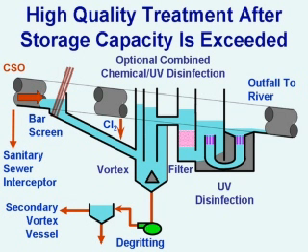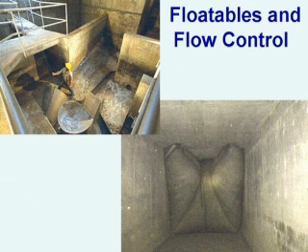If we remove a lot of the pollutants, we ought to be able to get the light to the water to disinfect the bacteria. The hydraulic profile of the high-quality side is shown in this treatment schematic. I should note that when the flow first occurs and goes into this facility, all those vessels are first filled up before any discharge occurs. And just filling up those vessels takes out about 600,000 gallons for this 1,000-acre drainage area, and it prevents about 20 overflows that used to occur. So right away, we've knocked the overflows from about 60 down to 40.